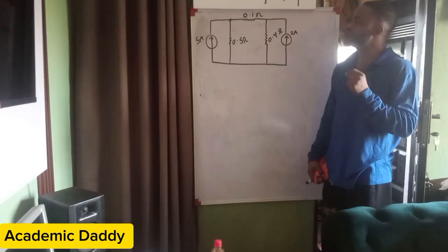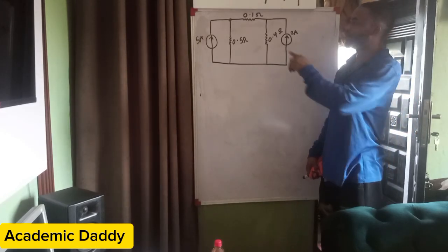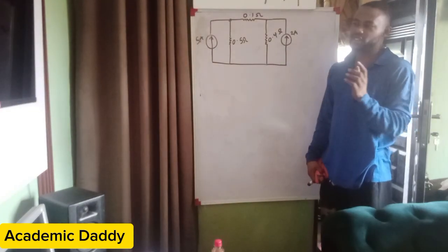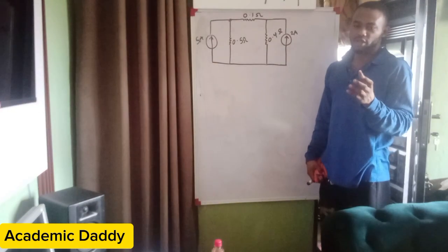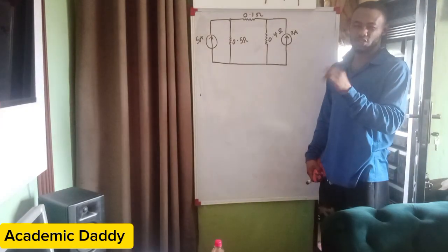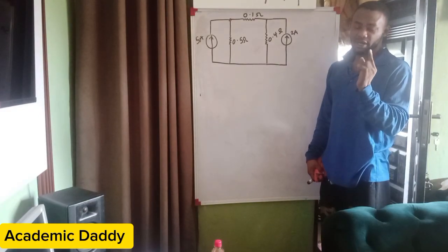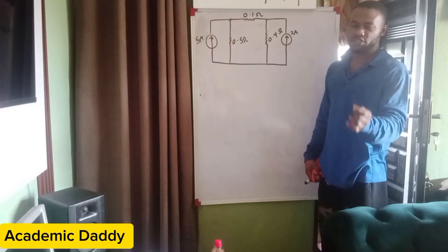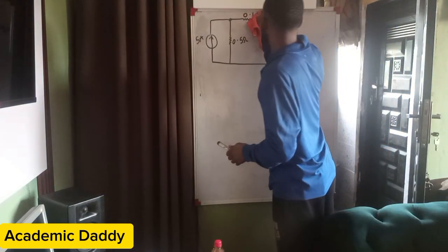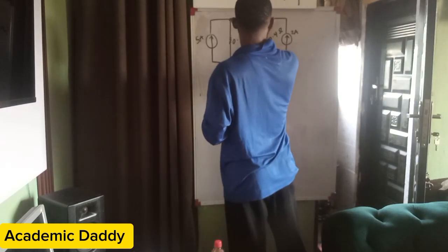The only thing they want you to prove there is that you apply Norton's law by saying that whatever resistor they are talking about, you short circuit it to become a wire. In the end, you remember that Norton's theorem states that in a linear circuit, every resistor and every current will become a parallel current, in parallel with the load resistor and the Norton's resistor. So if that be the case, let's apply it. This 0.1 ohm resistor becomes short circuited, so it becomes a wire.